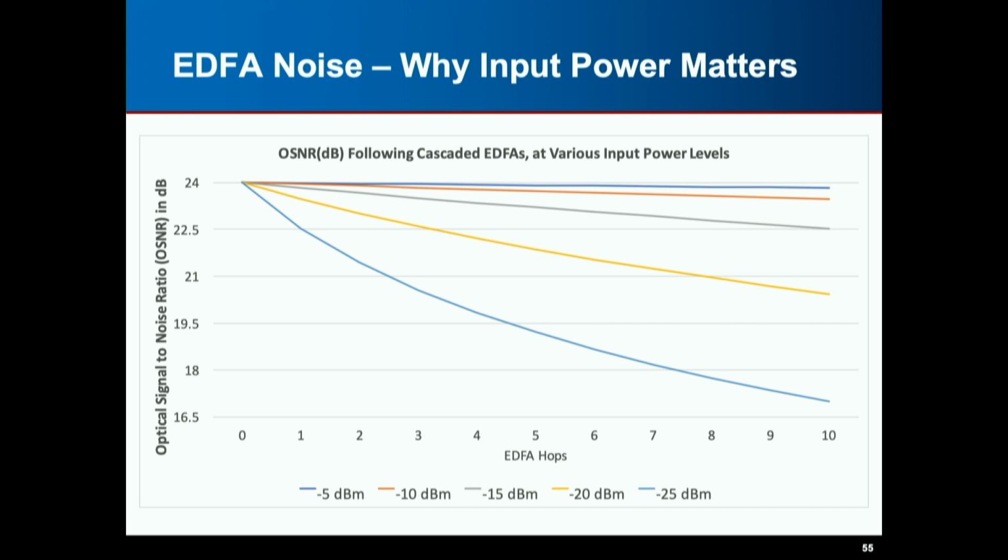You'd be able to amplify every 10 kilometers. Problem being that's really expensive and really difficult to do. So we try to strike a balance. We try to amplify enough to not let the signal be degraded, but you could let it go to 120 kilometers, but even though you amplify the signal and even though it comes out bright, because you let it get so low first, you've added a lot of noise to the system.